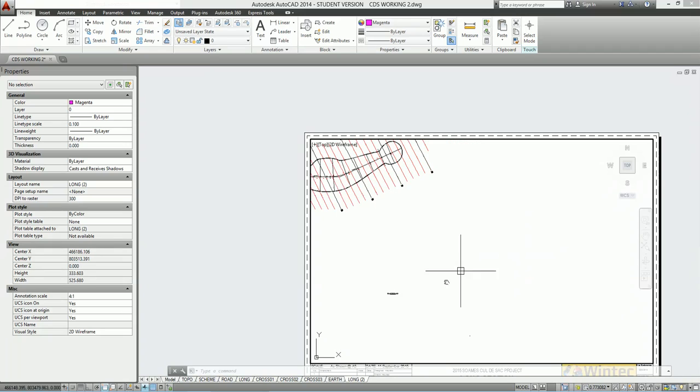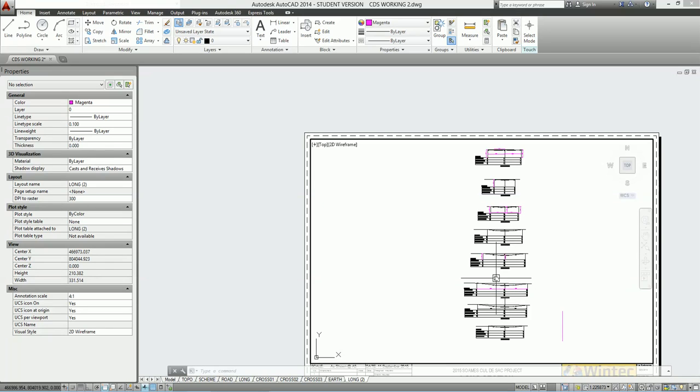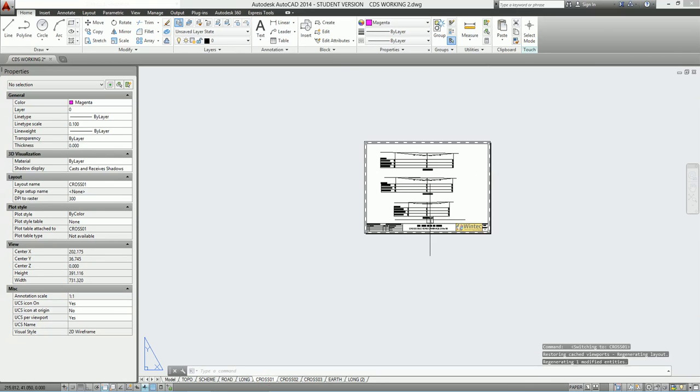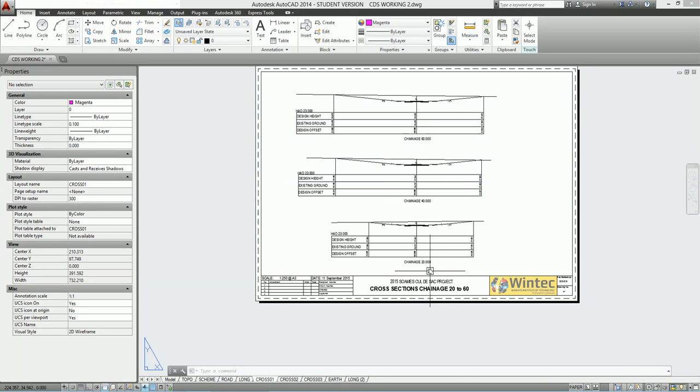to each cross section. So then we very carefully put the cross sections in order. I've worked out that I can get 3 on the first page, 3 on the next page, and 2 on the last page, so I've spaced them accordingly. Typically the centre line, you would run a line through the centre line so that they would all be on the same line, so that when you go to the actual lines or sheets of these, you can get a bit of an idea, if you look at it a certain way, as to what the road's doing. So it's sort of getting deeper as we go through here.